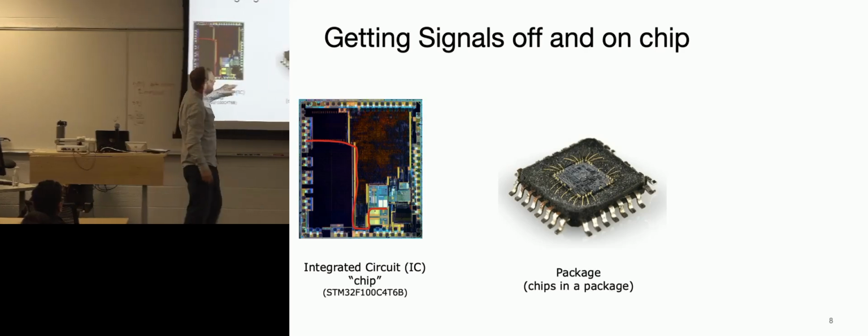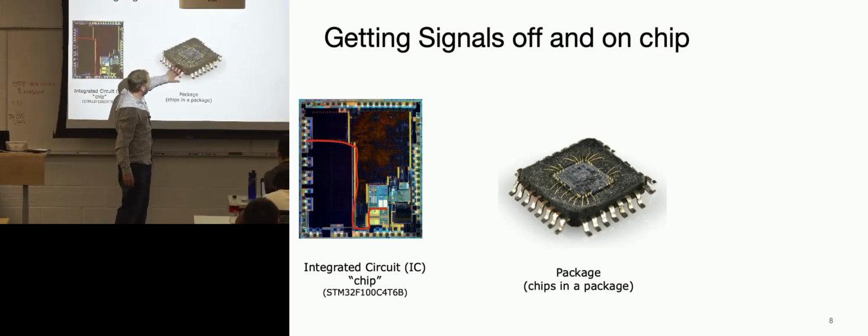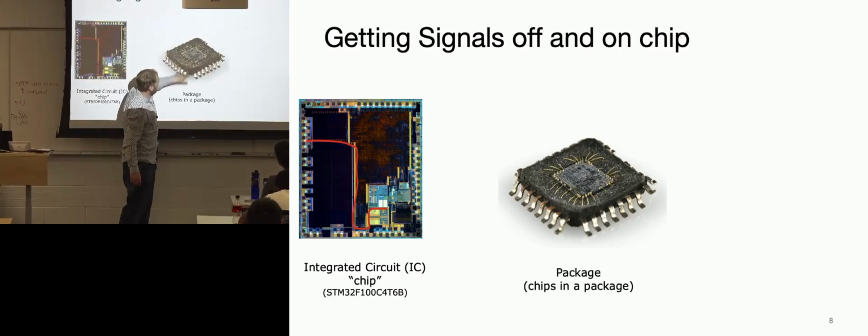These pins, this is a chip and this is a package. So this is a package, and then there's wire bond. There's a special machine that you need gold wires to be able to connect to silicon substrates. There's a little bit of chemistry involved that I don't really understand anymore. But then you use your wire bond machine to go to these metal things here. These are pins. The reason they're black is that they have to be insensitive to UV. You don't want UV hitting your chip or else you get bit flips. And this mechanically keeps it safe.